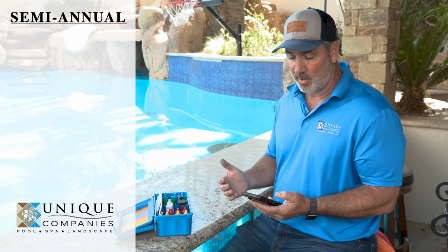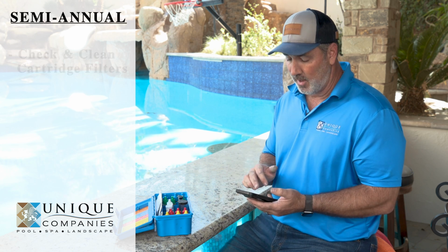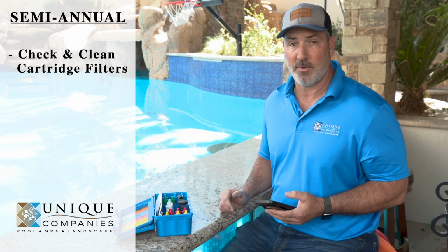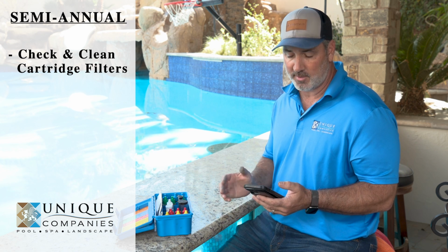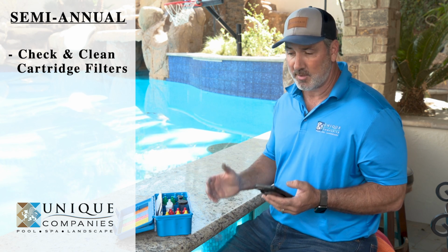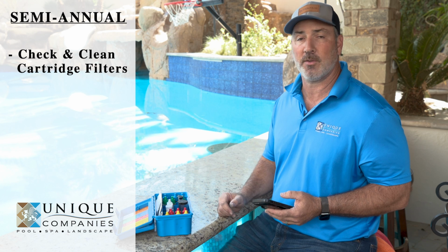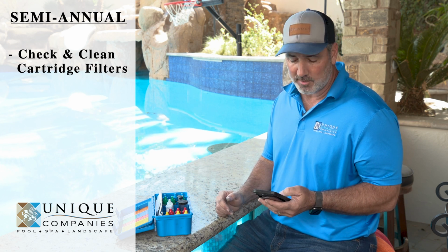Next, we go semi-annually, which is every 6 months. We need to check and clean our cartridge filters. So like I said, 95% of our pools have in-floor cleaning systems and cartridge filters. So typically we find that those cartridge filters need to be cleaned every 6 to 9 months.